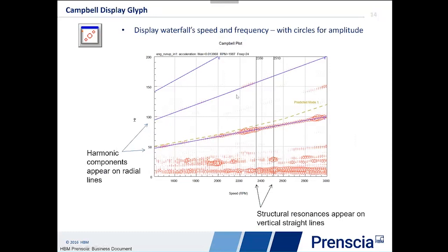And above that cutoff, depending on the energy, so that's the axis that's perpendicular to your screen, you've got those circles, whose diameter depends on the energy, right? So you can see orders sometimes in a clearer fashion, and you can put those order lines on top of them. So that's second order, fourth order, sixth order.